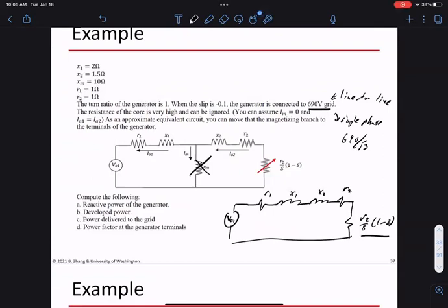The short answer is for type 1, you don't. So the grid has to compensate for it, or something else in the grid has to deal with this. For more advanced types, there are different ways to do it. For example, you can add a capacitor to this, right? You can add a variable capacitor to boost up the reactive power.